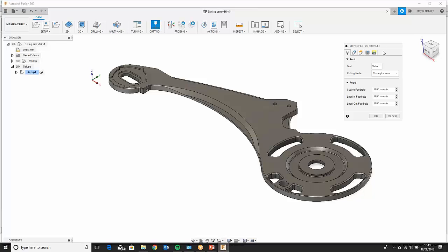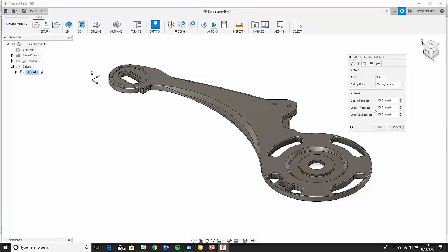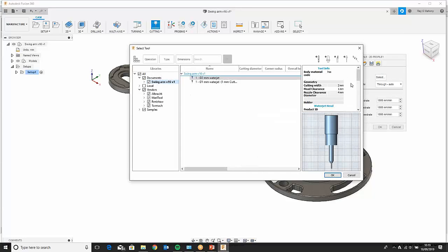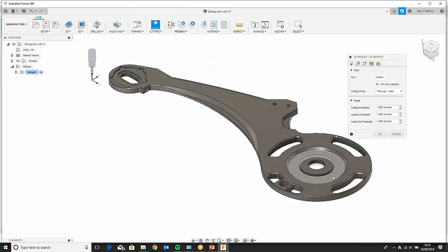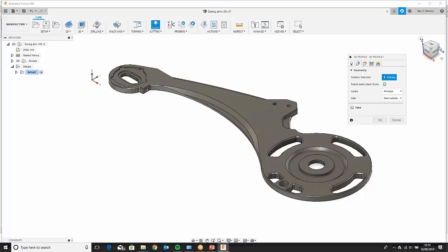This is very important to realize: within Fusion 360, we have a tool library, and this goes for Inventor too, I should say. It's a common tool library that we're able to select from, already available to us. For example, if I select the water jet, which I want to use for processing in this case, I now want to select the profile I want to work with. I come along and select the geometry.